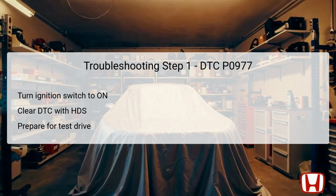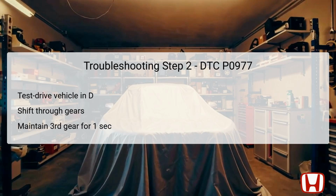After clearing the DTC, the next step is to prepare for a test drive to help confirm whether the shift solenoid is functioning correctly. Make sure the shift lever is set to the D position, allowing the vehicle to engage the automatic transmission system actively. You should then drive through the first 3 gears, allowing the vehicle to shift automatically between them. This process not only assesses shifting performance, but also helps identify any immediate issues.